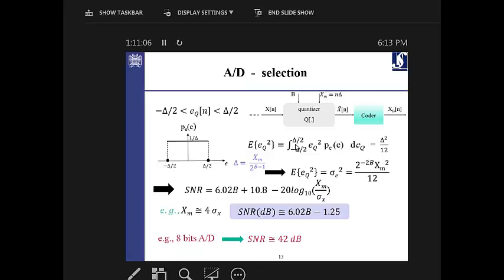It's clear? It's a distribution. Because it's a distribution, it should sum up to 1. It integrates to 1. On the other hand, we know the delta, when you have the dynamic range, based on b, we have 2 to the power of b number of levels, and we have the signs, plus and minus, so we just subtract 1 to show the sign. And we have the dynamic range of the signal, which is coming in the input. So that defines the delta.